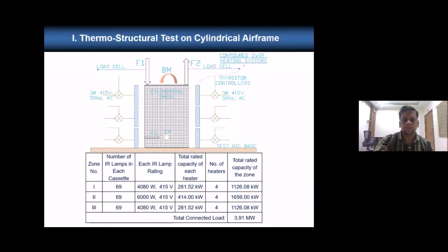So now coming to this, here is one cylindrical shell which is almost 1 meter in diameter and 2.2 meters in length. Here I have to apply a pure bending moment on this side. Then this has 4 cutouts at every 90 degrees. Then these are divert thrusters of 3 tons each. So I have to apply them at 90 degrees. A critical case, 2 thrusters of 3 tons at 90 degrees I have to apply. Now this entire setup I have to enclose with heaters also. So how to apply this? For this, we have used the internal surface, internal area, to apply this load.